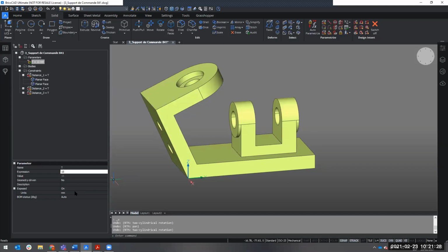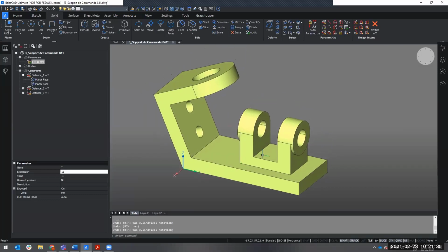And then we arrived at step 9, which is creating an angle constraint. So what you do for this one is you select here the icons, which are a little bit small, I realize that, but it's a box with like arrows in there.